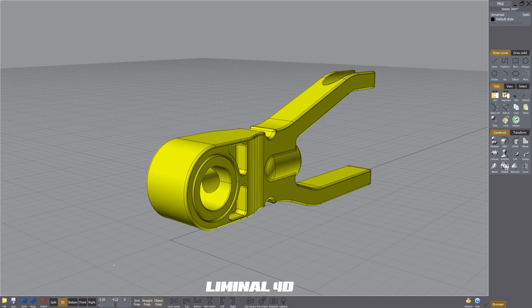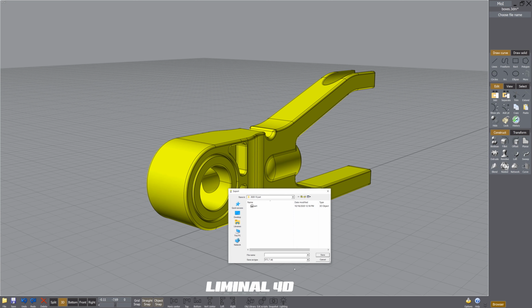In this video, we are taking a look at export settings for 3D printing. Go down to the bottom, File, hit the Export button. This dialog pops up. You give it a name. You choose the file type. For this tutorial, we are going to select a .stl.